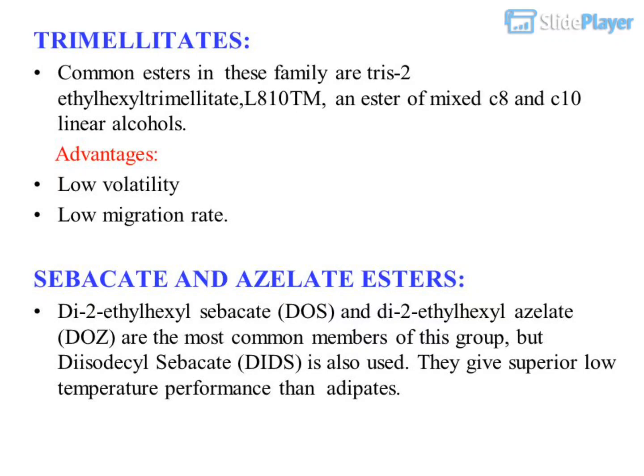Sebacate and azelate esters. Di-2-ethylhexyl sebacate, DOS, and di-2-ethylhexyl azelate, DOZ, are the most common members of this group, but diisodecyl sebacate, DIDS, is also used. They give superior low-temperature performance than adipates.